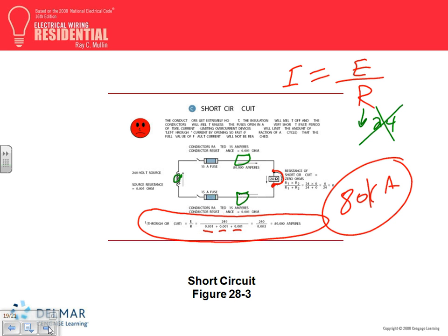Why? Because we need the conductor impedance to be very low, guys. Otherwise, the voltage drop will be high. So I always bring this one up later on, guys. Next quarter, I want to tell you the advantage and disadvantage of having longer runs. What's the advantage of having the load right next to the panel? Voltage drop is 0, nothing. What's the disadvantage? The short circuit current is extremely high.